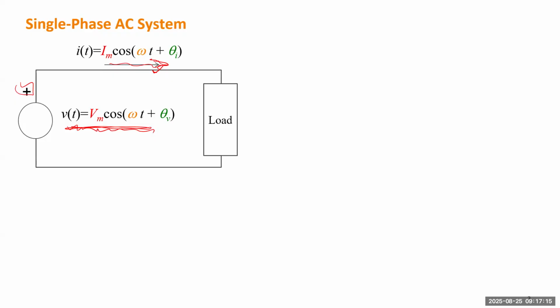The other equipment we'll just call a load. Usually load means the current comes into the terminal which has the positive sign there. The positive sign just matches the positive sign of the source on the same side. So with current coming into the positive terminal, that equipment will be treated as a load. Similarly, whether that device really behaves like a load, we don't know. We still need to do some calculation, because a battery under charging condition is a load, but under discharging condition it will be a source.